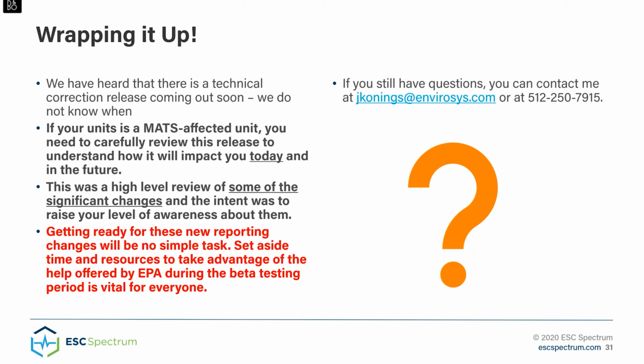The second question is, the diluent downtime isn't included in the Mercury rate downtime, correct? I think you're asking if you're using a diluent monitor as part of your calculation for the mercury emission rate, then if the diluent monitor is unavailable and not producing valid data, and therefore you cannot calculate a valid hourly mercury emission rate, the diluent monitor does impact the downtime reported for that monitoring system because it is a component of the system. I hope that clarifies.